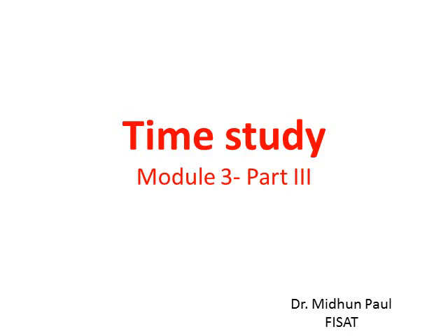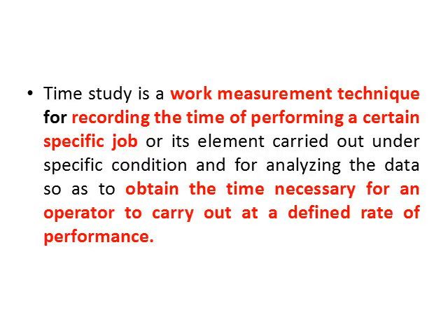For doing the method study, while we are dividing the entire job into small components, we need to measure the time of each component, right? That time measurement is usually called time study. So time study is a work measurement technique for recording the time of performing a certain job.